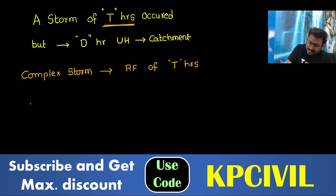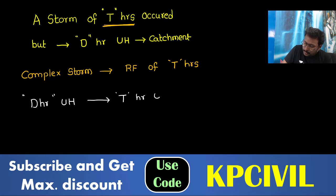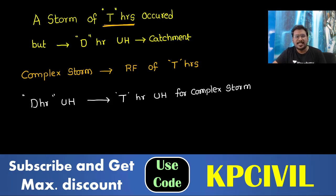So using this D hour unit hydrograph that you already have for the catchment, you are plotting the T hour unit hydrograph for the complex storm. That hydrograph method is called complex hydrograph. What is the confusion? D hour unit hydrograph, T hour unit. What is the confusion here?